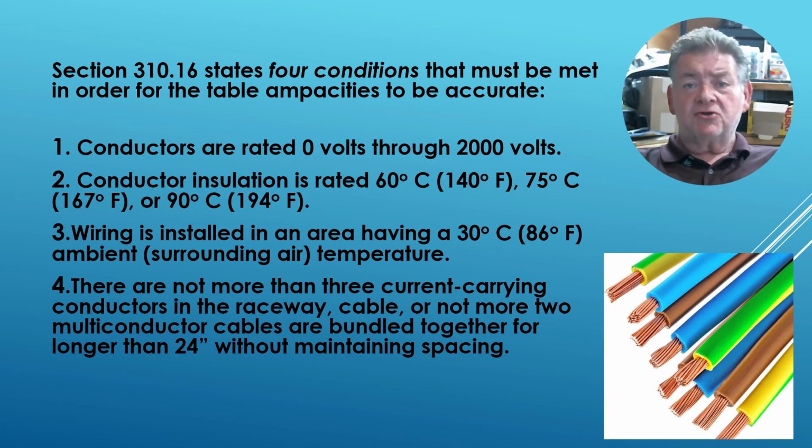For a commercial job, commercial fit up, many times you're using metal clad cable, type MC. Now, you pull your cables and then you go back and you want to properly secure them. If you have multiple cables, many times you tie wrap them or use bridle rings or whatever method of support you happen to be using.